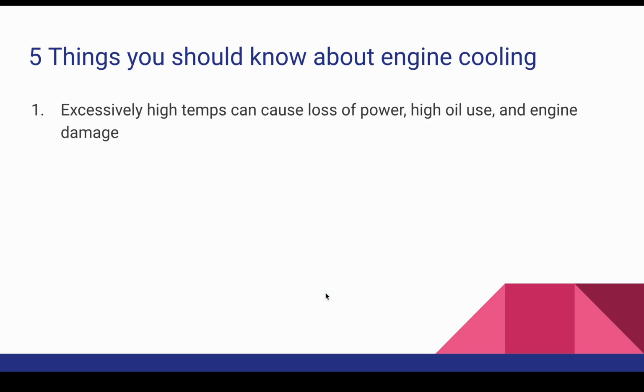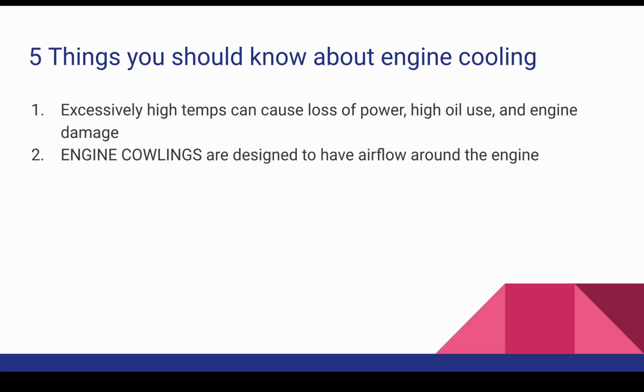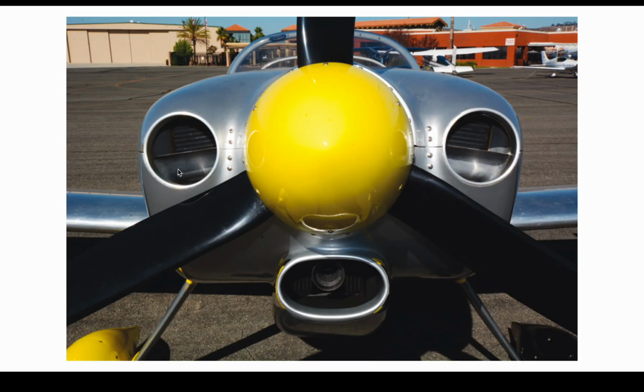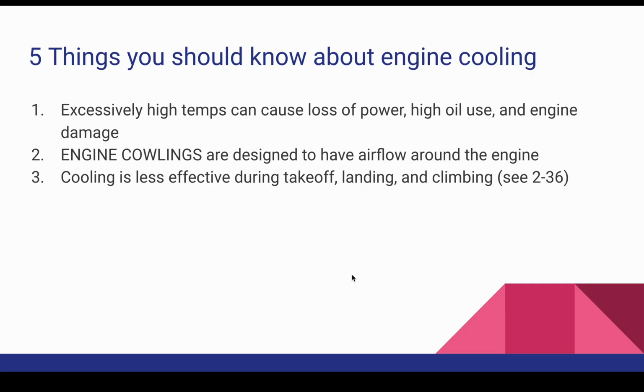Five things you should know about engine cooling. Number 1, excessively high temps can cause loss of power, high oil use, and engine damage. Number 2, engine cowlings are designed to have airflow around the engine. Number 3, so this is intakes for this airplane. Okay, and it's bringing in, this plane looks like it's surprised that we took its picture, but really these are just ports that pull in air for cooling. Cooling is less effective during takeoff, landing, and climbing. We'll talk about that in a little bit.